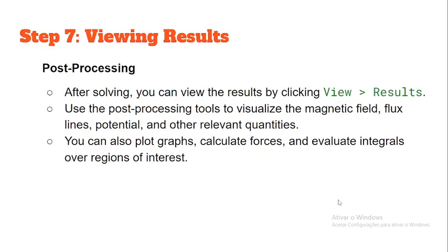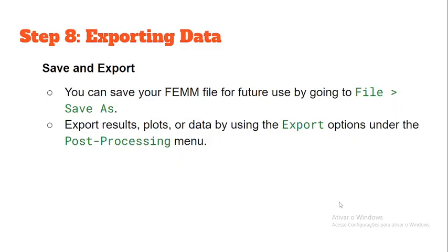Step 7. Viewing results. Post-processing. After solving, you can view the results by clicking View Results. Use the post-processing tools to visualize the magnetic field, flux lines, potential, and other relevant quantities. You can also plot graphs, calculate force, and evaluate integrals over regions of interest.